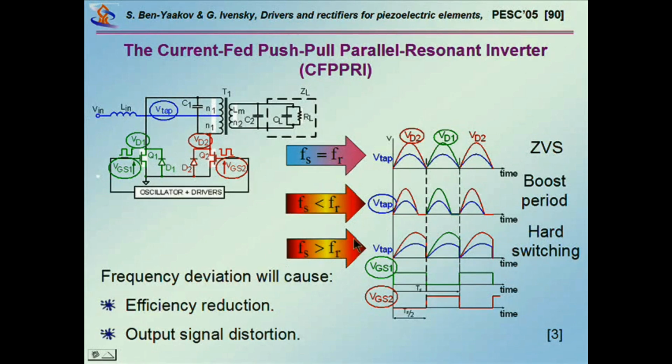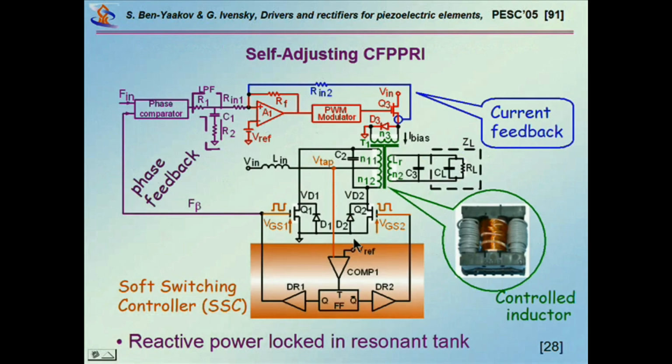So what can we do? Well, there is a solution to that, which we have implemented, and it works very nicely. There are two stages here. One is this little circuit, which is, by the way, commercially available, and this circuit will synchronize the switching to the resonance. It will automatically switch the transistor whenever the voltage goes back down to zero.